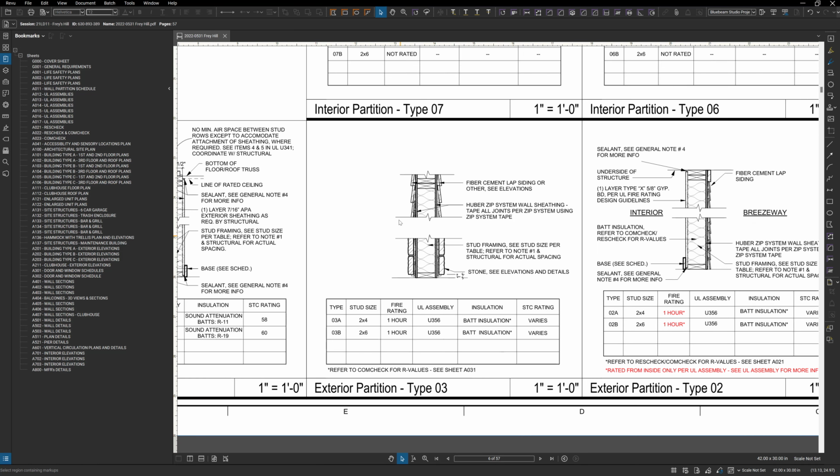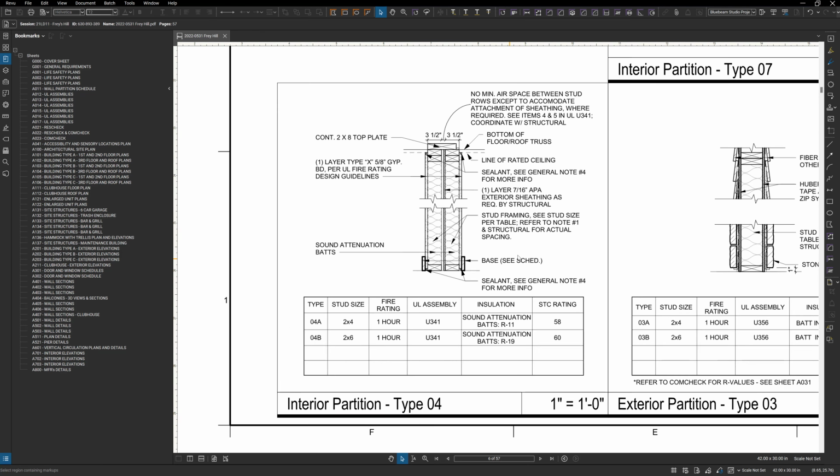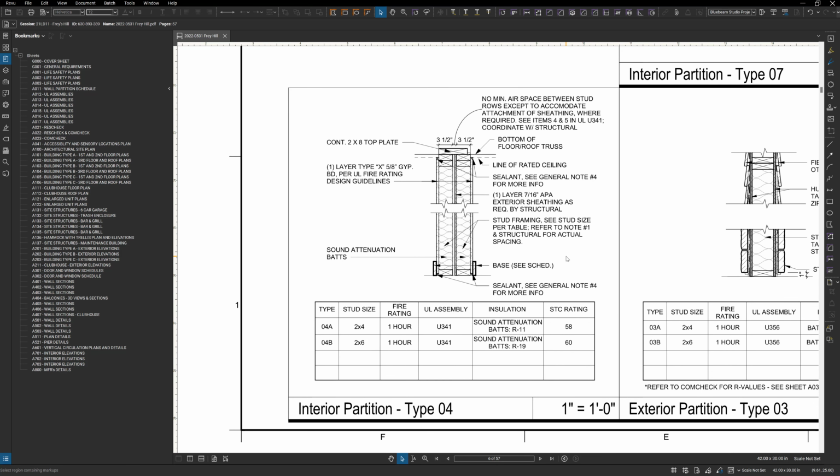This is just a placeholder from when we got exterior materials on both sides of the wall. It's used for 1% of the whole job. These are our demising walls. They separate units from each other. The reason we like this one, the reason it's a double wall, is explicit. It's for sound. It works great for structural as well, but our main reason we love it is that it's really, really good for sound. Keeps it quiet between you and your neighbors. It gets a sound transmission class, STC rating of almost 58 or 60, depending on which one you're using.